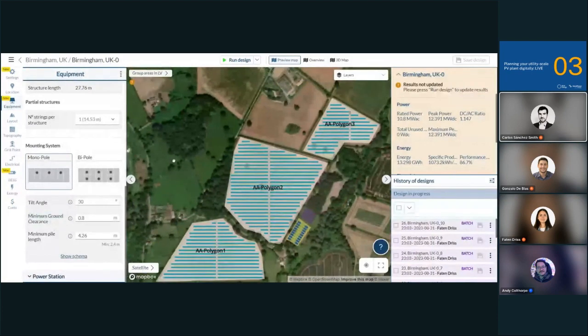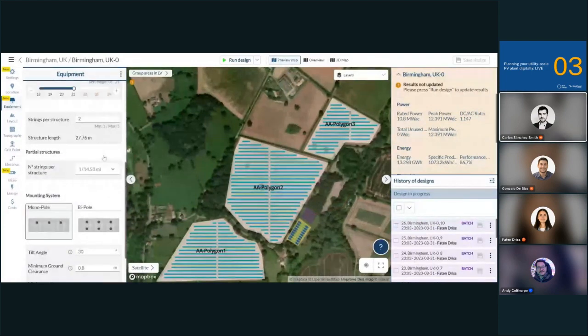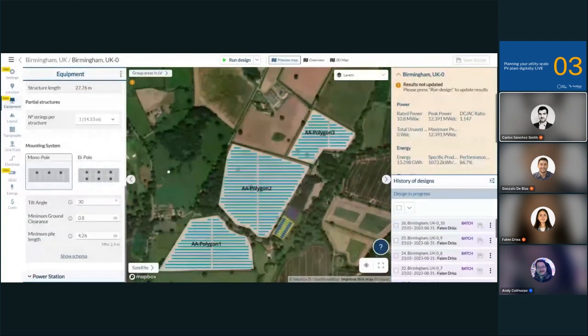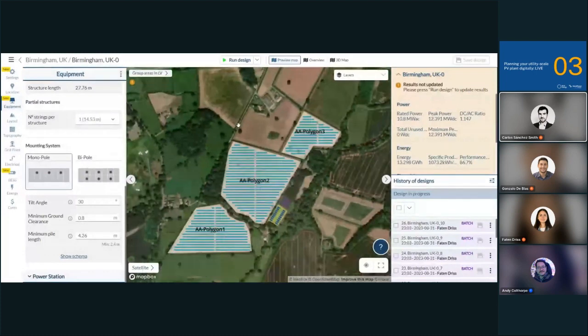Yes. So normally, well, it's been proved that by increasing the height at which the modules are mounted directly, it increases the amount of incident backside radiation on the bifacial panels. So this basically allows reflected light from a larger surface area to reach the back of the module. And for fixed structures, with the aim of reducing cost and increasing efficiency, I've tested that 0.8 is quite optimal in terms of levelized cost of energy. So we are increasing the energy that the panels produce and also having a really good levelized cost of energy.